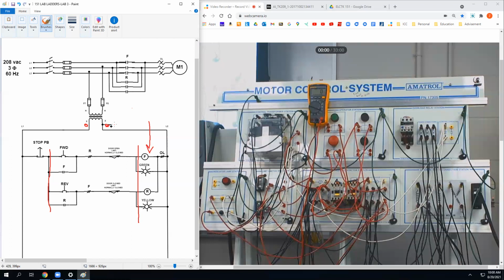So what if Zach's output back method told me to check in that cabinet over there on this motor starter coil? But the stop push button is right in front of you and it's already open. Might as well just put your meter leads on.